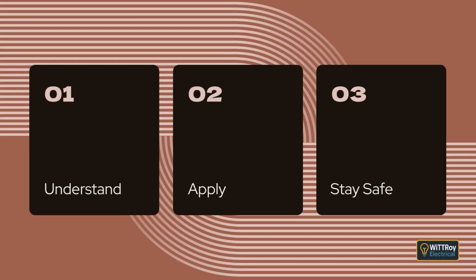Clause 2.5.4.4, Omission of devices for short-circuit protection. This clause lists cases where short-circuit protection may be omitted. These include circuits where disconnection would be dangerous, certain consumers' mains installed in specific ways, cables connecting generators, transformers, or batteries to switchboards, provided the wiring is arranged to minimize short-circuit risk and the protective device is located at the associated switchboard. In summary, short-circuit protection may be omitted only when the wiring method itself keeps the risk extremely low.